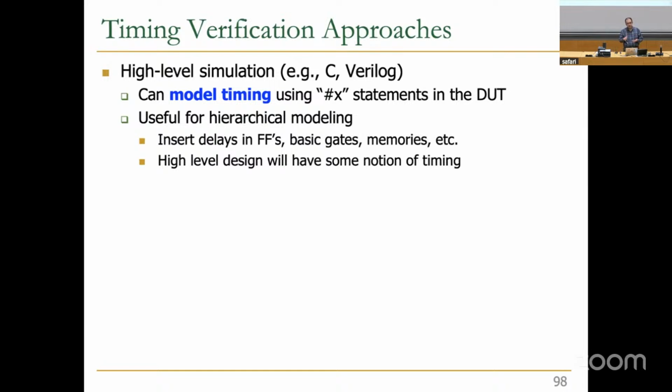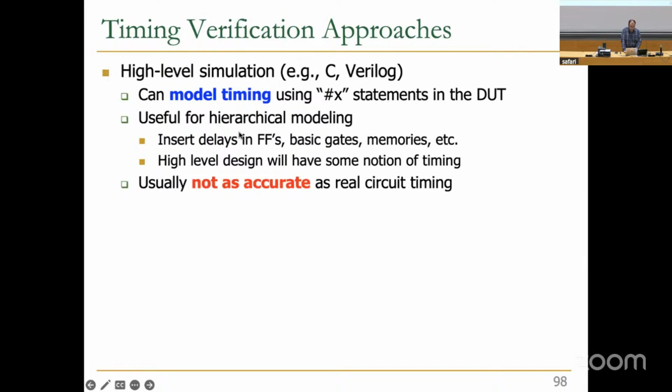And after synthesizing your circuit, your HDL code, when you synthesize it to gate level or to gates that are defined in your cell library, then you can do simulation, which is post-synthesis simulation. And in that, if you open that Verilog code, you can see that all these values, minimum, typical, and maximum latency of gates, flip-flops, everything is annotated in that Verilog code. In order to make sure that when you are simulating this circuit, you're considering timings of all these circuits. And that can help you to verify basically timing violation or not in your circuit using simulations.